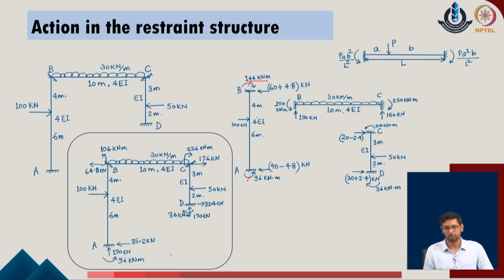One of the values is 144, another is 96, as these have an imbalance, or the net moment is available in the given system. So, with respect to the given loading, we also add the contribution of the net imbalance moment, which will be balancing the couple of the given problem. In the same case, we can evaluate these values for the second member and the third member of the given system.